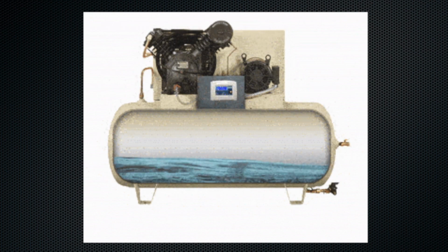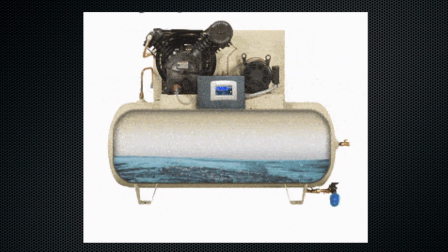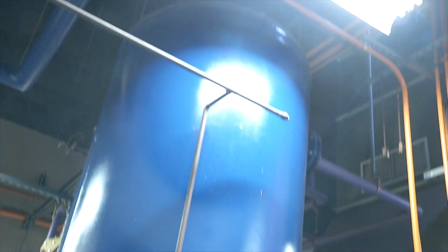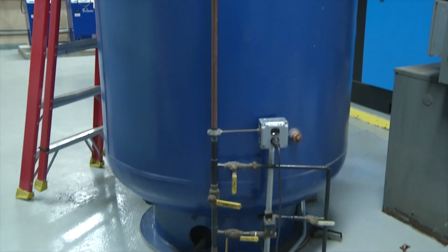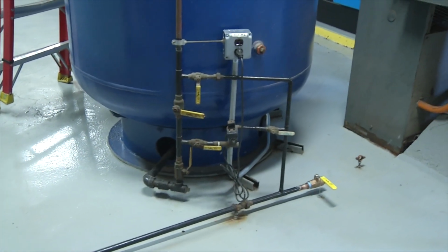Okay, now what do we do about these dryers? Well, the first thing some companies do is to try and dodge having a dryer at all by saying if I've got too wet air, I'm going to let it settle in a storage tank and collect the water from the bottom. Or I'm going to control the moisture by bleeding air into the system as opposed to using a dryer. Time will not permit me to go into the number of reasons why these are bad ideas. And sometimes it's why are you using compressed air in the first place if you could use fans to replace them. But again, another advertisement for our next episode. Just know that in normal cases, you need low dew points of 35 or 40 degrees or less.